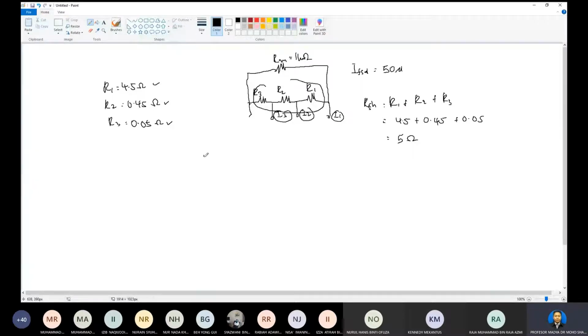Okay, to calculate the R shunt equals Rm over (n minus 1). Given this, we get 5 ohms. And then with Rm, we have to calculate the Im. First we have to calculate the n first. Given this, n equals, using this formula, 1k divided by 5 plus 1.